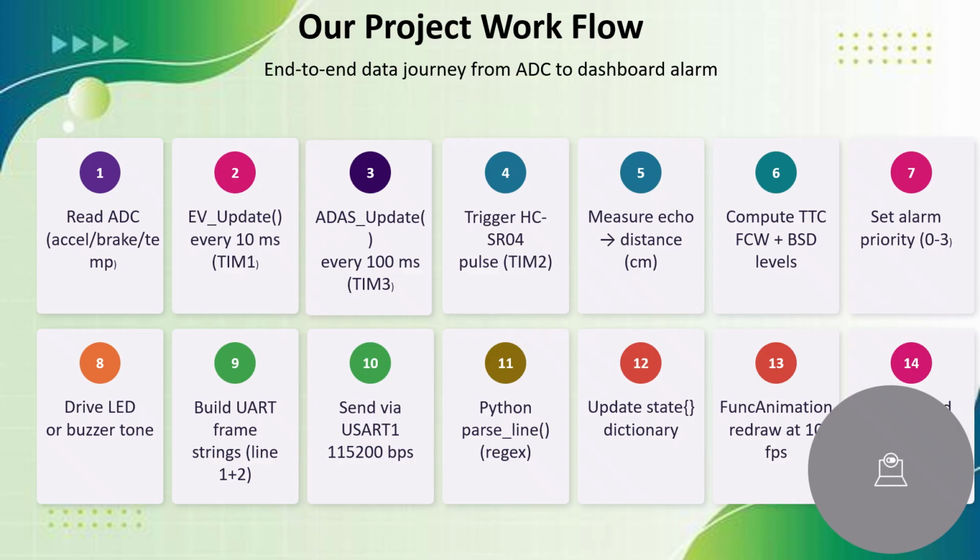These are the flow of our project. First read ADC, second EV update, ADAS update, trigger HC-SR04, measure echo distance, compute TTC, FCW, BSD level, set alarm priority, drive the LED, build UART frame, send via UART serial, 11th Python parse line, update the state dictionary, and at the last we have to implement it in the Python dashboard. So there is the successful execution of our project using these slides, and hence we have successfully completed